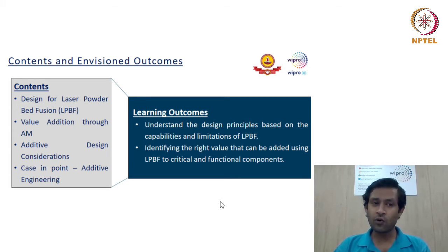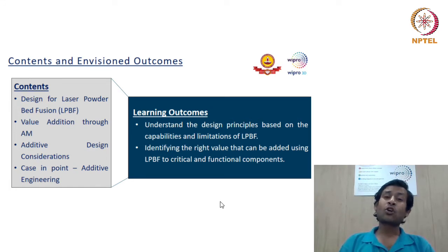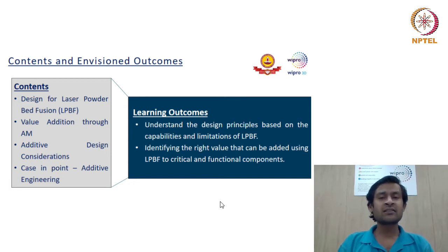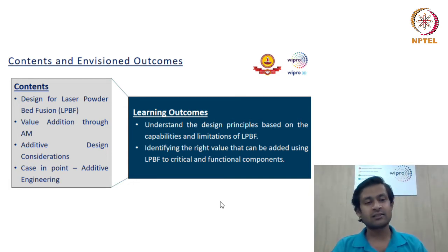So this session will focus on laser powder bed fusion and the value addition that can be done using laser powder bed fusion process. The value addition can range from mass customization of a single component to lightweighting in series production or low batch production, or making lightweight components and high performance components for rocket engines, or to make satellite components to perform in cryogenic conditions.